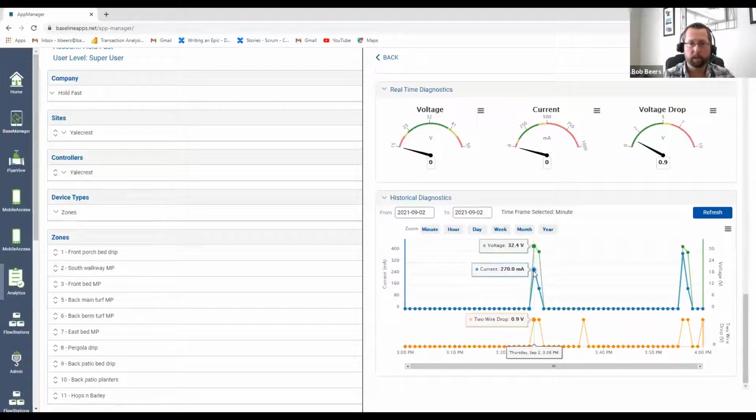And then there's information you can infer here too. As you see, your inrush might be going up or down. Why is that? Is the solenoid getting old? It's a new site. Maybe you just inherited this site, and you've retrofitted it. You now have a baseline. And this can help indicate what types of solenoids might be out there if you haven't done specific checks. Just looking at the data, you could start to infer this information and be able to track it.